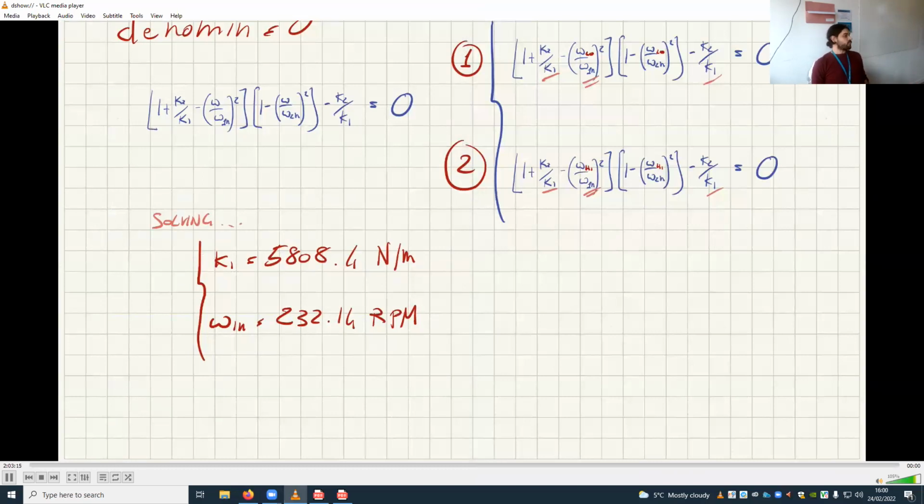Now, I would argue that an engineer who designed this would have known the operating range of the compressor and would have made sure that there was something in place. So every time you put in a vibration absorber, it's generally to correct an issue. Millennium Bridge, same thing. Renault Formula One car, same thing. In that case it's a bit different because you can't predict all the possible things going on, but you can always tune it to the natural frequency of the oscillation so that when it gets driven at that oscillation, you know it's zero.